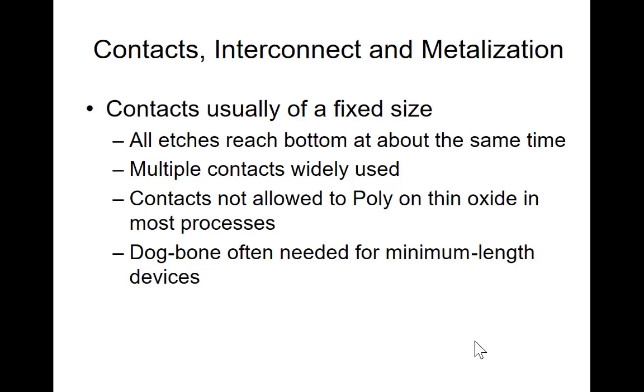So originally near the silicon wafer at a very lower level, you have your silicon substrate itself, and you have the N wells, and you have the P wells, the N diffusion, the N active, P active areas. Then you need to make connections to the metal 1 level. So you make your contacts so that they are connected to the metal 1.